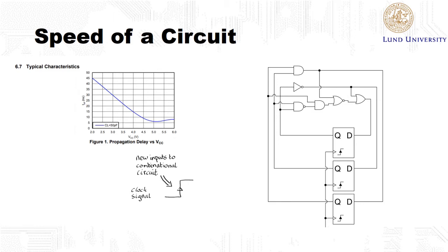For our circuit to operate properly, the combinational circuit must generate logic values for the next state before the next positive clock edge. That is, the inputs must propagate through the combinational circuits before the next rising clock edge. To determine the maximum clock speed, we calculate the worst case propagation delay.